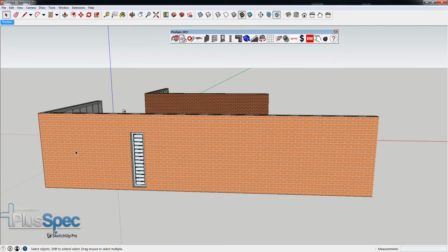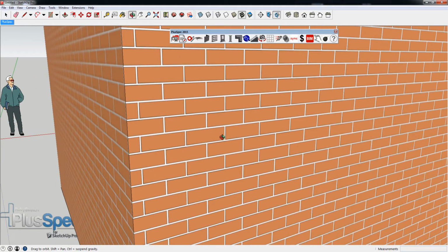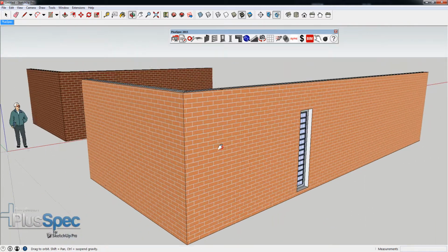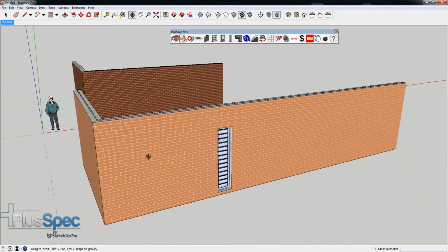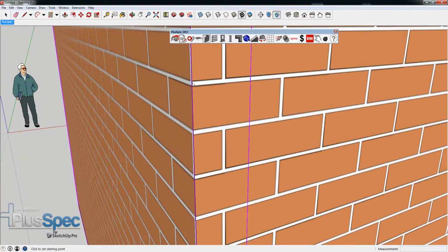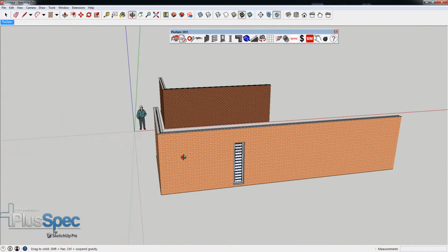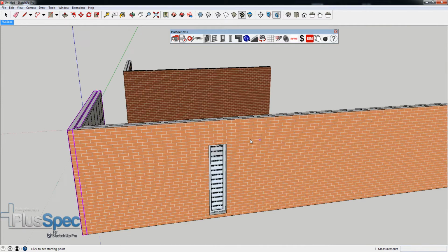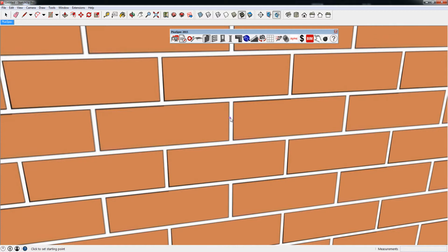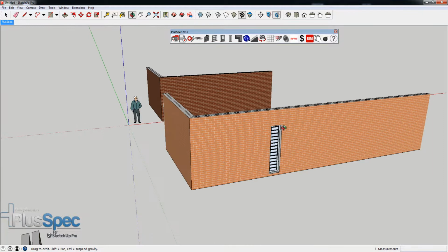It depends on the length of the wall, and you'll notice down here that I've got a quarter brick. It's good to design to suit brick sizes, but if you don't, that's up to you. This does help you do that. So if I wanted to get this correct, I can just drag this wall back to suit my actual brick sizes. So I might say, you know what, I actually want it to work brickwork. So I'll go to here. And now I'm working brickwork, so the bricklayer is going to be happy, and the job's going to run a bit quicker. Don't be too worried about it with a long wall like that, because they actually stretch the perps, so you've got a maximum and minimum allowance of perps. On a small wall you don't want to have cuts.